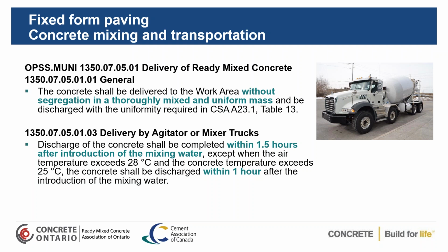Now, when you're delivering the ready-mix, you want to make sure it has no segregation and it's thoroughly mixed in the unit. And I just mentioned earlier the need to have your ready-mix trucks inspected to ensure that the fins are clean and not worn, because the better the fins are, the better the mixture that you get when you're doing your pavement. It gives you a better consistency.